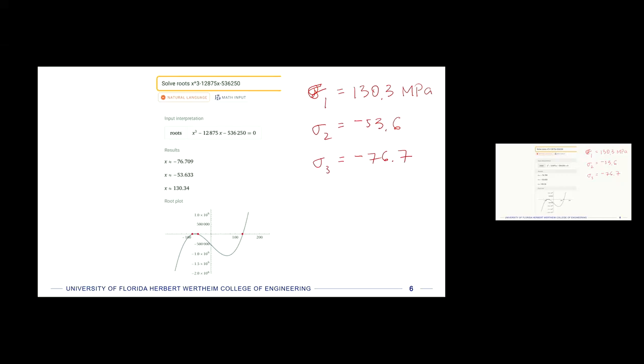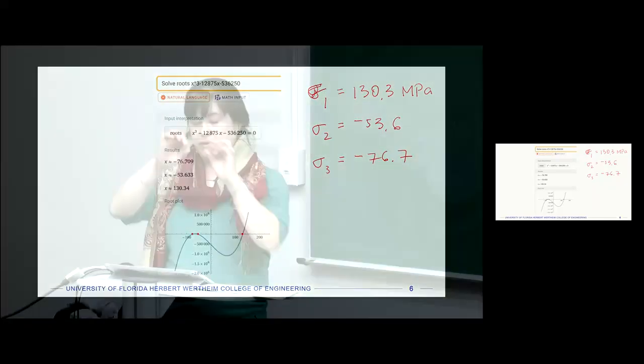So what this means is that we had our cube in x, y, and z, and in order to come up with the generalized stress equation, we cut it with an arbitrary plane. If we rotate that stress cube such that all of the shear stresses go to 0, and we're only left with the normal stresses, these would be the normal stresses. So the cube rotates, and then each face would have these coming off of it.